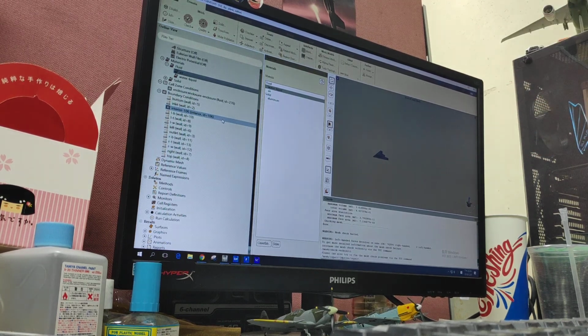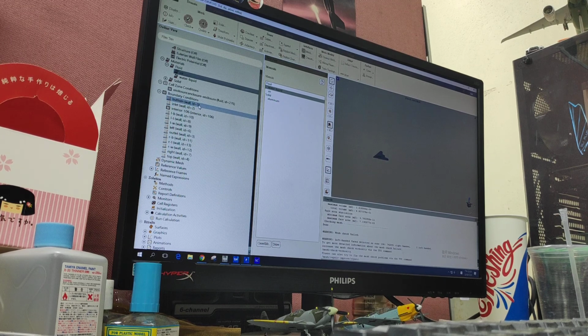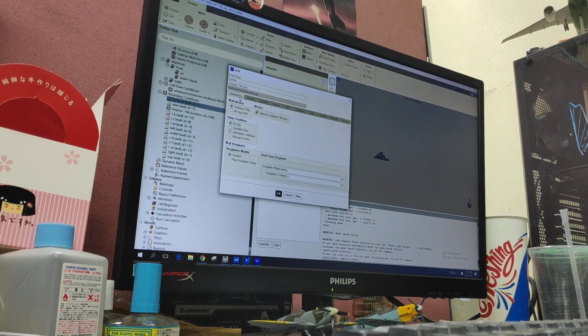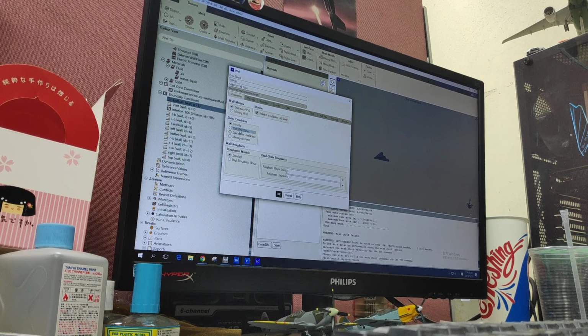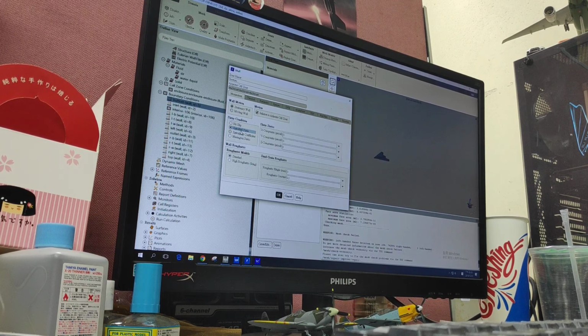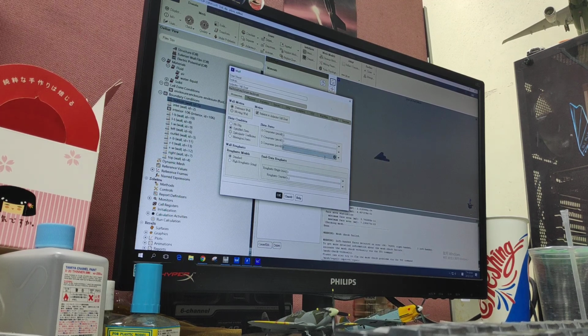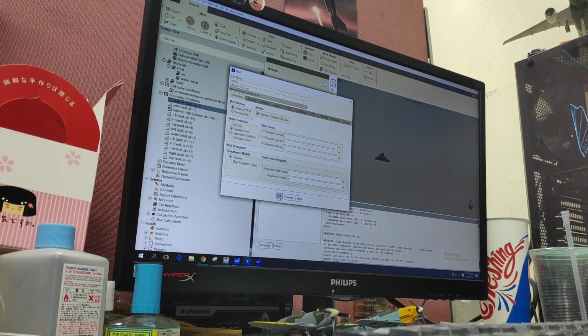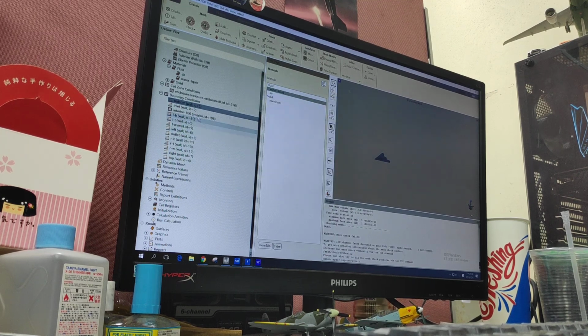Now for our bottom, click two times. We can find the method is wall, and then here specify shear. All of it is 0. That means free slip. So there's no friction, no no-slip condition.